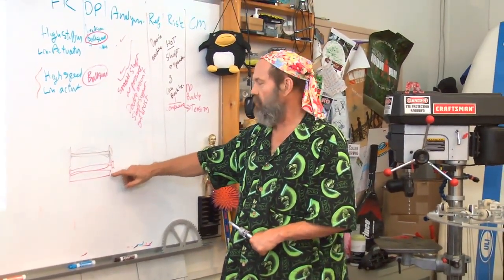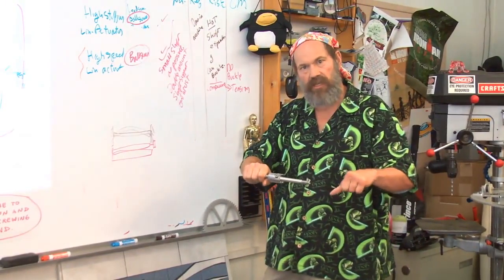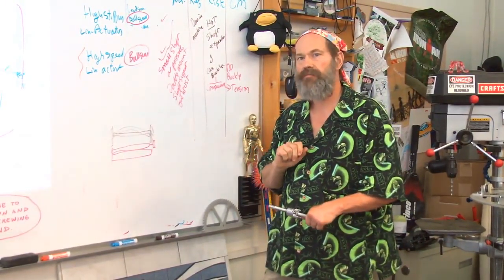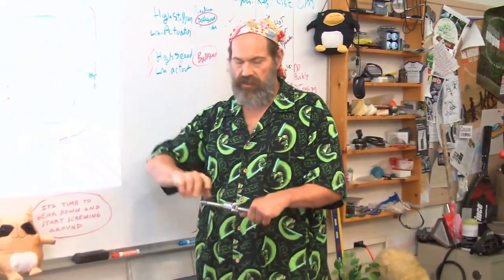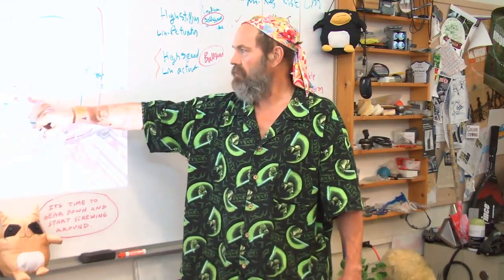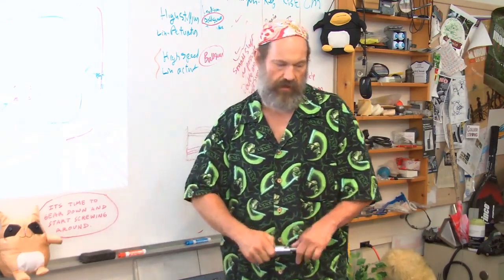And as long as my thermal expansion is less than how much I pre-tensioned it, the screw will always be in tension a little bit and it will not buckle. And if these are high quality rolling element bearings, the amount of drag I will get from the force placed on those bearings is low.